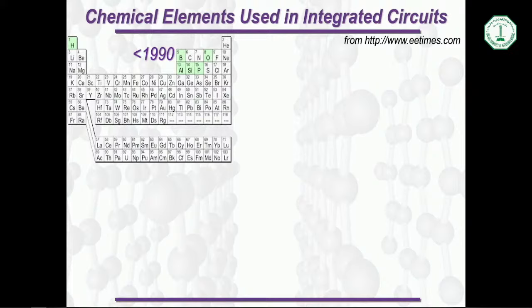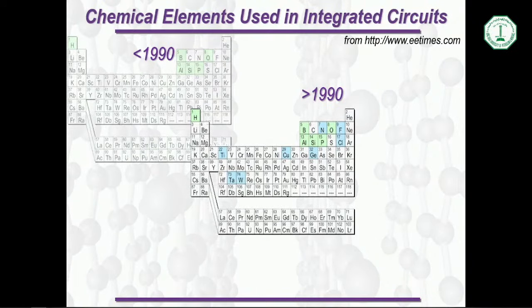Very basic, so even I could probably do it. Then, as the transistors became smaller and smaller, we started to use copper interconnect, so we needed some diffusion barriers and some work function matching material. So we started to use a bit more elements in silicon technology, and we had to adapt to the new requirements, but it was still manageable.